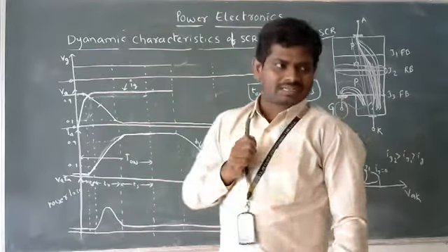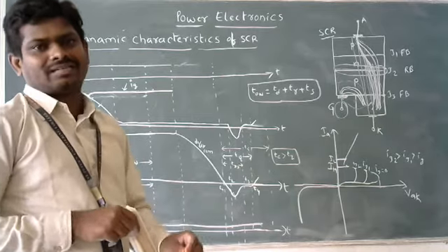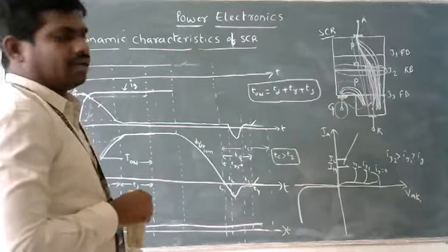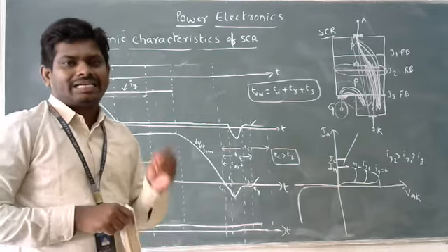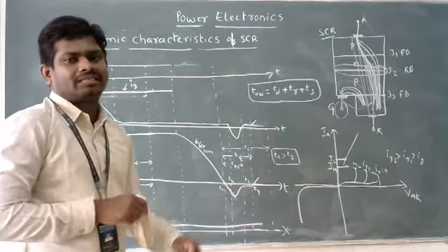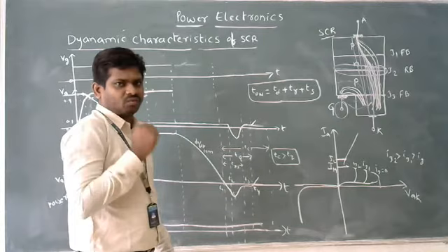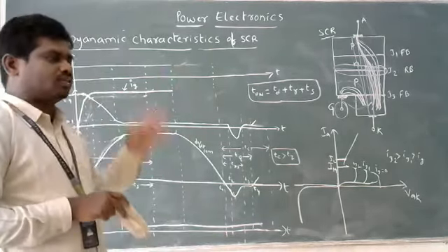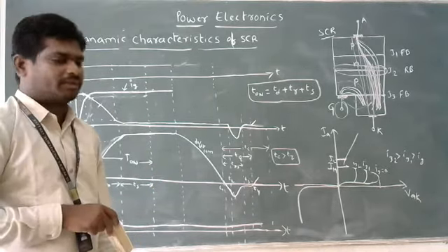Now our aim is to remove the excess charge carriers at the outermost layers and at the J2 junction. If we remove them, the SCR comes back to the forward blocking state. To remove the charge carriers at the outermost layers, we simply apply the commutation process.